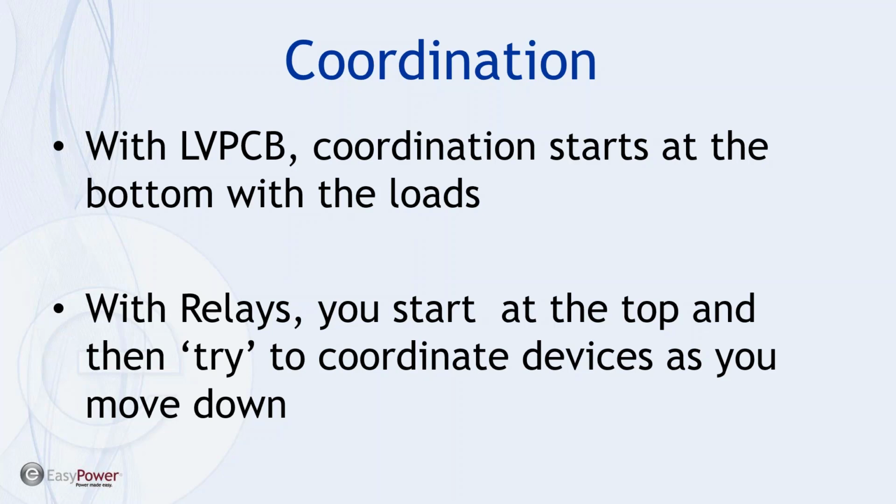And the reason for this is that we basically set on the very first relay an instantaneous protection that is guaranteed to keep whatever fault, if it exists, away from the transformer. So the idea is to protect the equipment as much as possible, and we'll kind of see that as this develops.